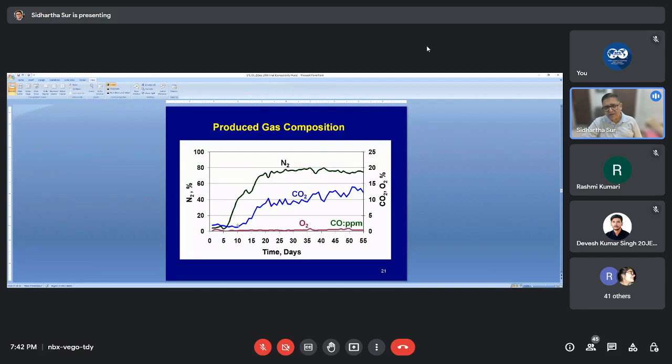So till the path through which the flue gases are traveling gets saturated with carbon dioxide, you won't see any evidence in the production well. So it's very low in the production well. But slowly it builds up to the stoichiometric level of 15 to 16%. This confirms that combustion has set in.